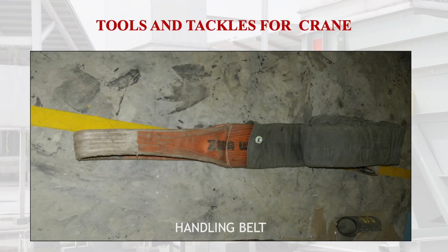Tools and tackles for crane. Any handling process or application of a crane needs tools and tackles for tying up the job or lifting the job. Therefore, they are also as important as the entire crane. Why? Because this becomes an integral part of the handling system. This is one of the areas where very little attention has been given, even though they are defective. In Indian industries, operators continue to use them due to work pressure or non-availability of new tools and tackles.